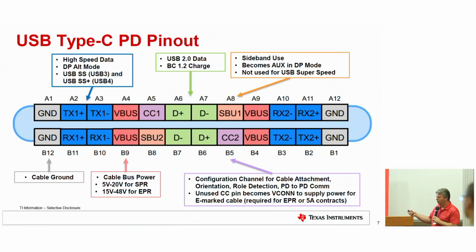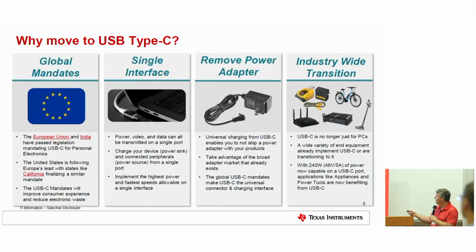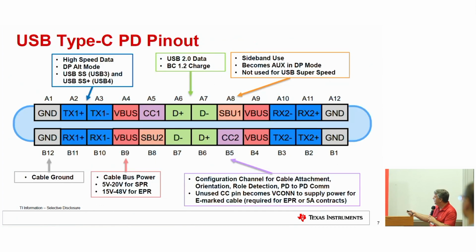So Thunderbolt 4 needs a Thunderbolt 4 cable. A lot of it has to do with the speed because you're going much, much faster. You need to query that the cable is capable of that. So there are cables for Thunderbolt, and it guarantees that. And it guarantees it has all the lanes. Not every cable has to have all the wires running through it, right? But a Thunderbolt 4 cable is going to have all the TX, RX, and all those wires guaranteed to be running through it.